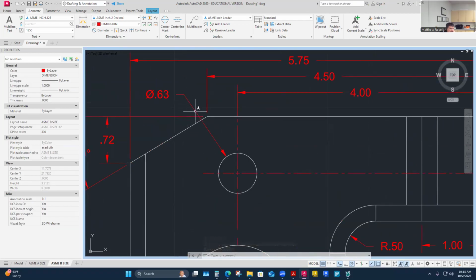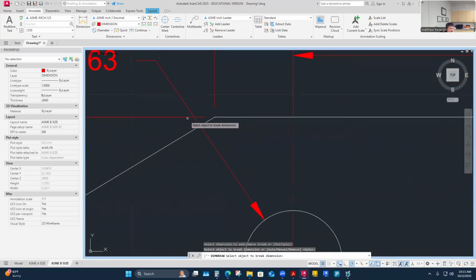I consider this a dimension line and this an extension. So if I'm going to break this, I'm going to break this for sure and around this. And I got to do that twice because there's the angular dimension. And you can see that if you zoom in, it's almost like it's got two. I can see it. So I'm going to break it again and I'm going to grab this one and this one. That's kind of hard to do every once in a while because